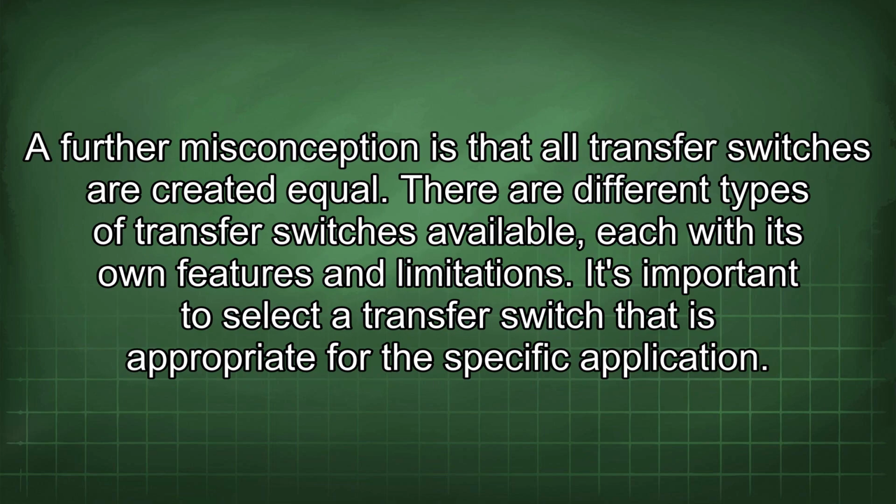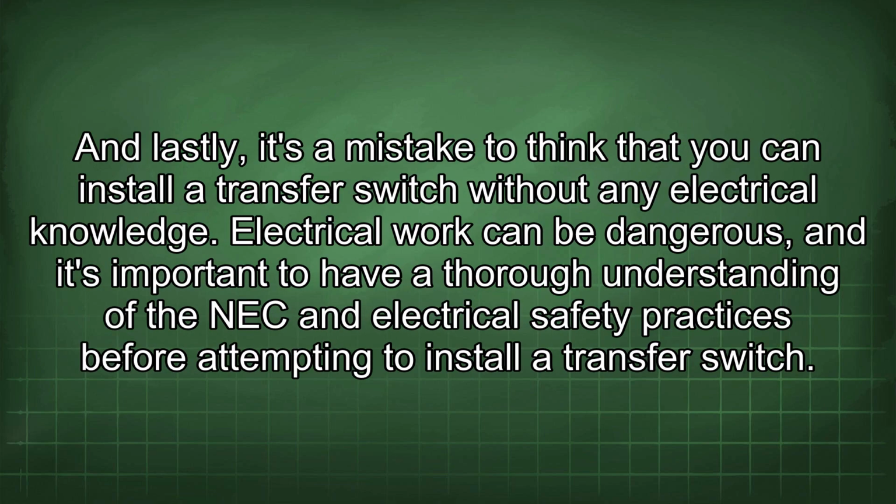A further misconception is that all transfer switches are created equal. There are different types of transfer switches available, each with its own features and limitations. It's important to select a transfer switch that is appropriate for the specific application. And lastly, it's a mistake to think that you can install a transfer switch without any electrical knowledge. Electrical work can be dangerous, and it's important to have a thorough understanding of the NEC and electrical safety practices before attempting to install a transfer switch.